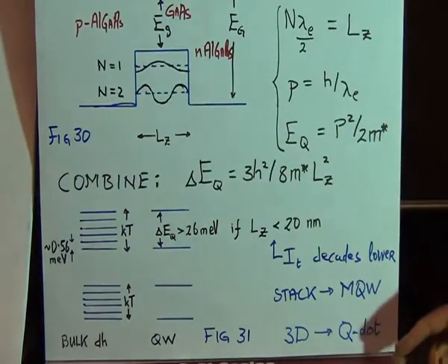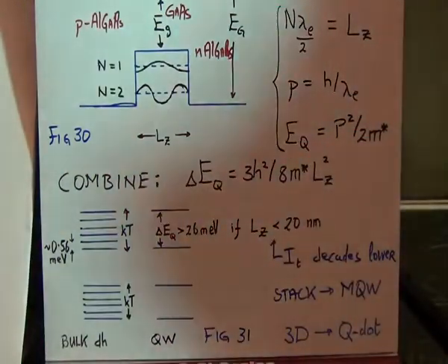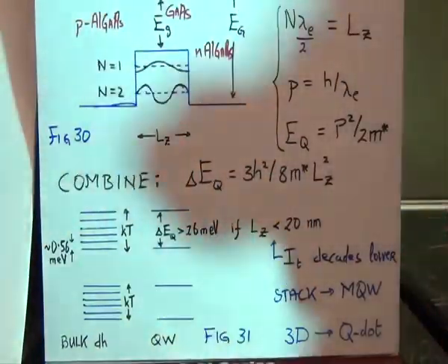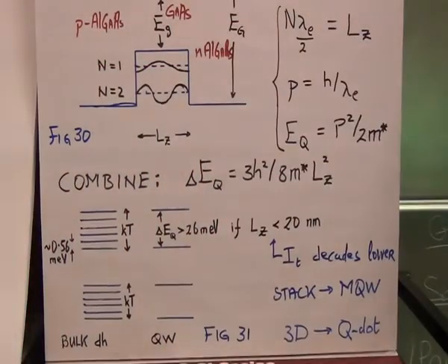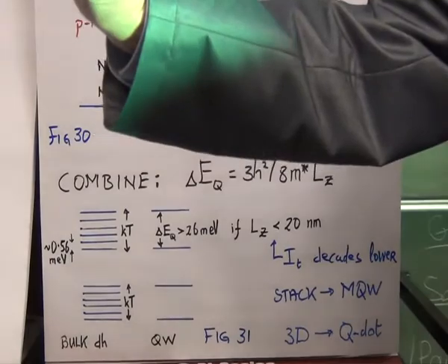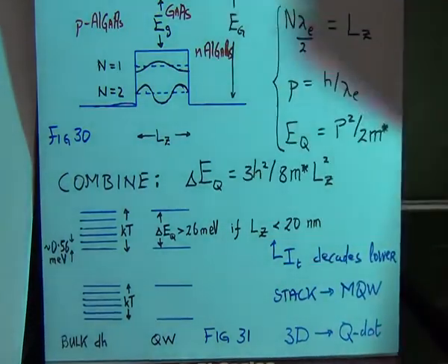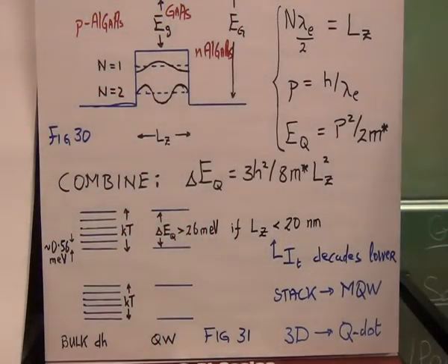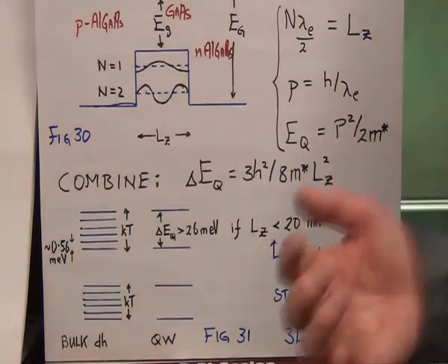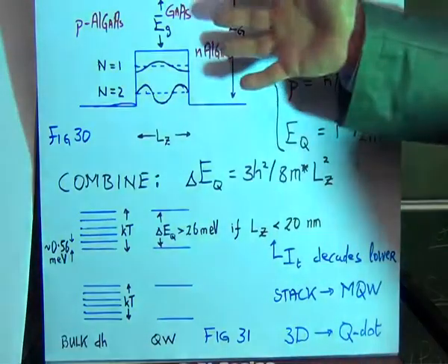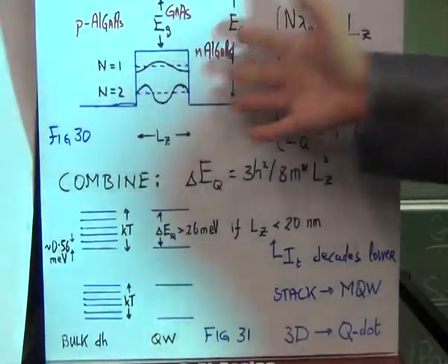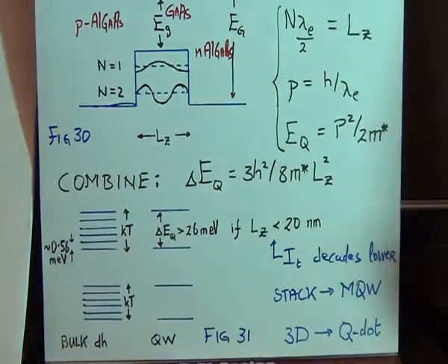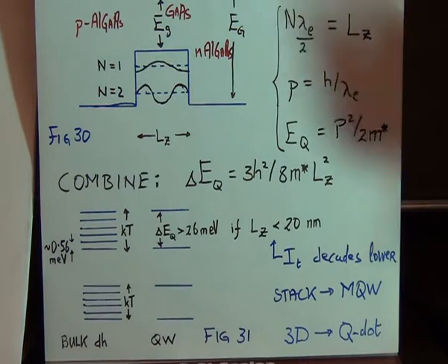They've even reproduced this process by confining, as well as confining in the Z direction, you can confine in a second direction, in 2 dimensions, and then instead of a quantum well laser, you'll end up with a quantum wire. And you can confine it in 3 dimensions, and you end up with a quantum dot laser. And these are all steps towards getting the tiniest threshold so that we can build these photonic computers. However, it's nothing abnormal today to see these kinds of devices, and they are moving their way into telecommunication systems as we speak.